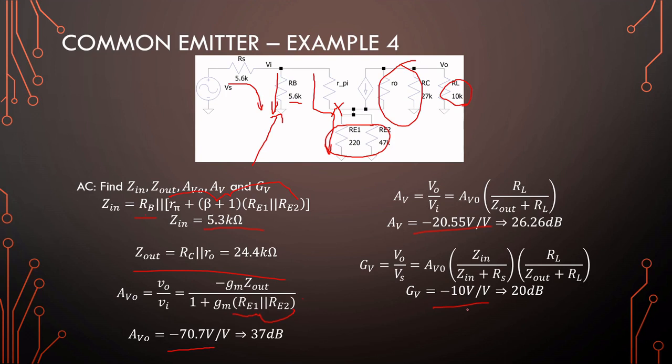Right, so here we can clearly see the effects of our loading. So this is one of those amplifiers that we can design for a matching input impedance very easily. Although the output impedance is not matched in this case, and we have major losses because the output impedance here is much greater than the load.